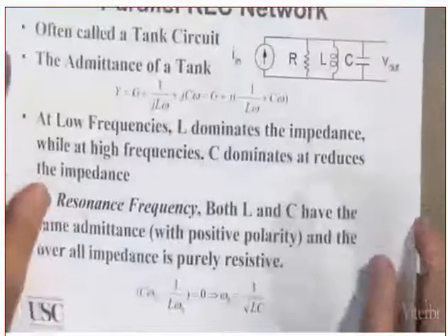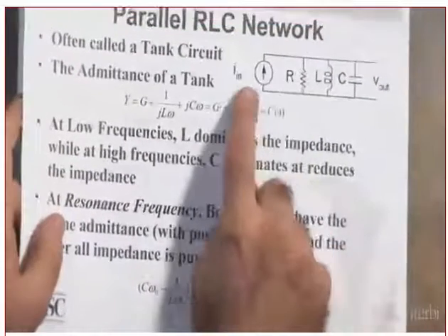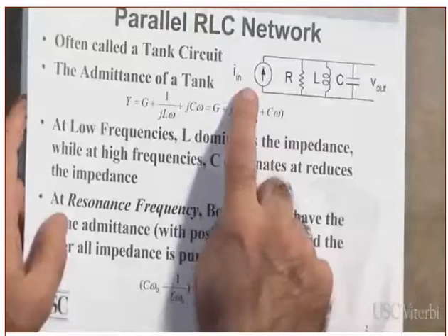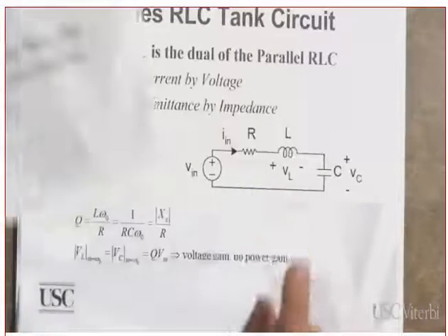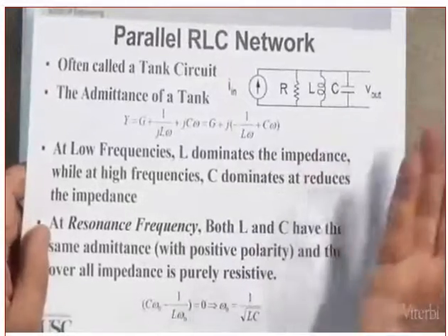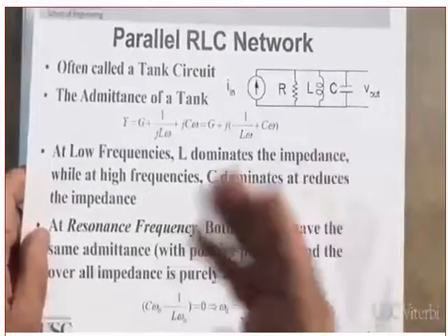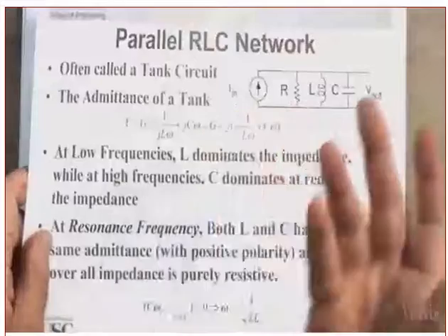Okay. For a parallel circuit, it is easier to work with using the Norton's type rather than the Thevenin's type. In here, you cannot talk about voltages. Why? Because all the components are connected in parallel, which means they have the same voltage.